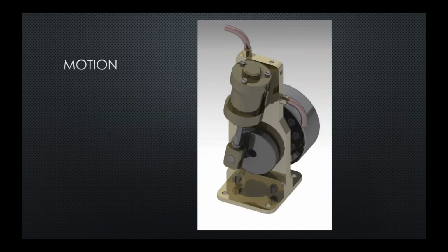And finally, we have here the final product. We can see here altogether, after going through all of the individual pieces, we have the inlet for the steam that goes through the guided holes in the frame, traveling into the piston cylinder, which would then move the piston up and down along the crankshaft, oscillating the cylinder to the left and the right as it moves around its cycle.